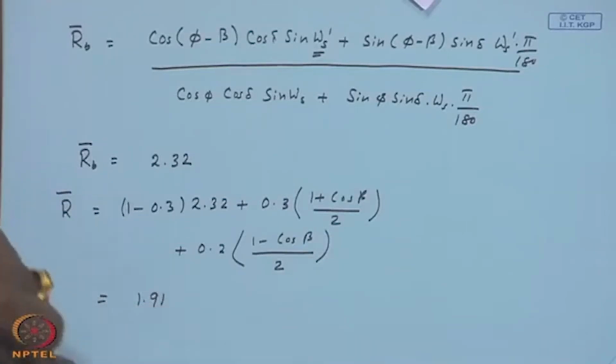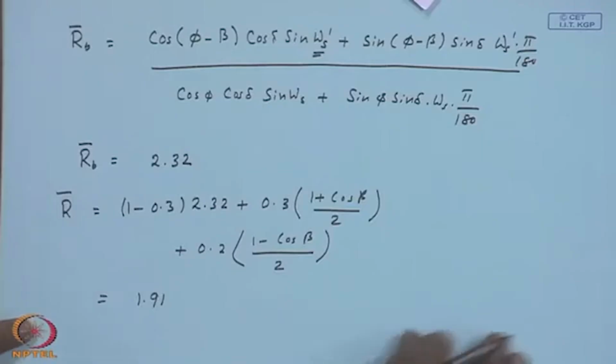Let us just halt for a while. So, in the course of this problem so far, we used how to calculate the declination, how to calculate H 0 bar and the clearness index, and then the diffuse fraction and the parameter R bar. So, tilted radiation, diffuse fraction, extraterrestrial radiation and declination, these relations have come so far.